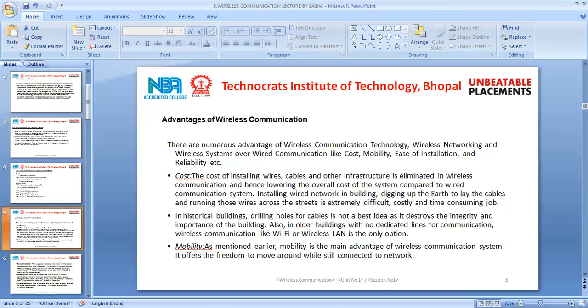Sometimes these will be in phase with the main signals and will add to it, increasing its strength. At other times, they will interfere with each other. This will result in the overall signal strength being reduced. So multi-path fading can be detected on many signals across the frequency spectrum, from the HF band right up to the microwaves and beyond it. It can cause signal to rise and fall in strength.